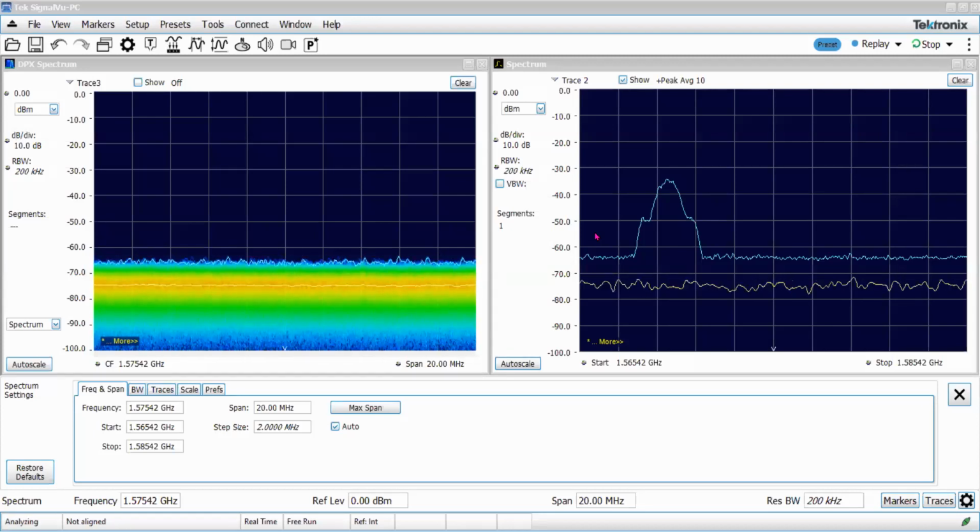Is there any open source tools available to analyze GPS signals after collecting GPS data? Yes, you can download some MATLAB source, but you need a front end. So you probably have to write your own software receiver. At least you have to write some code to do the signal acquisition. And when you need to do signal acquisition, you must know how to generate the PRN code. So please try generating the PRN code yourself. I have a very detailed handout, so I can upload this later. You can see and try.